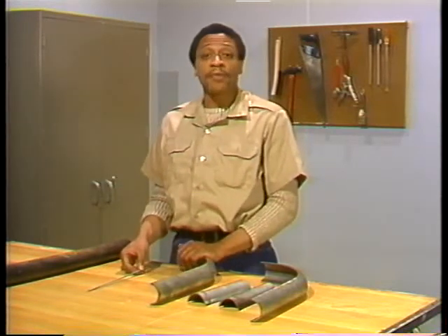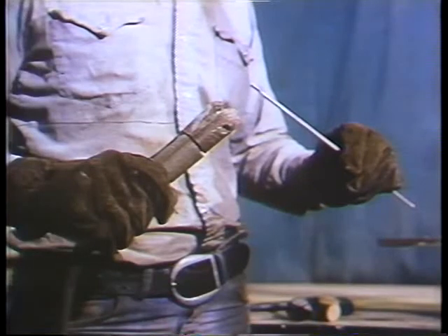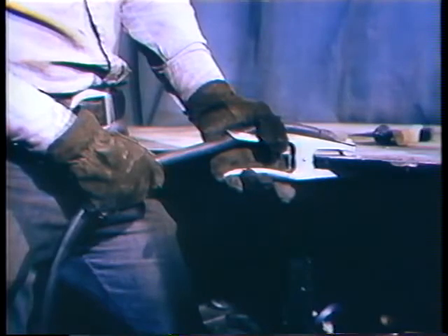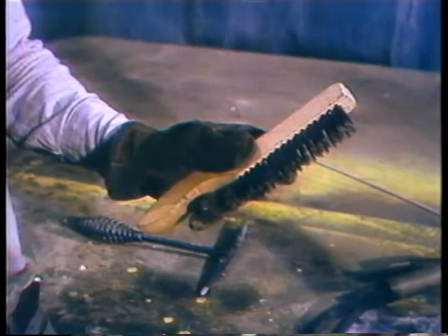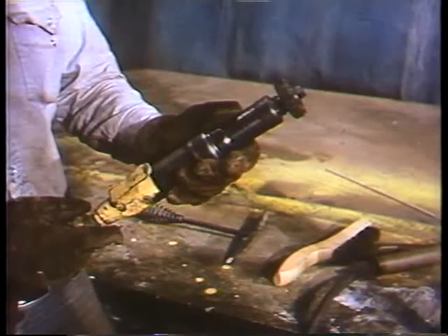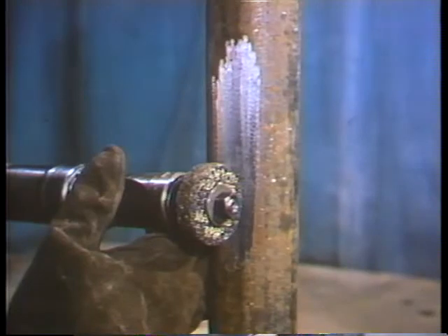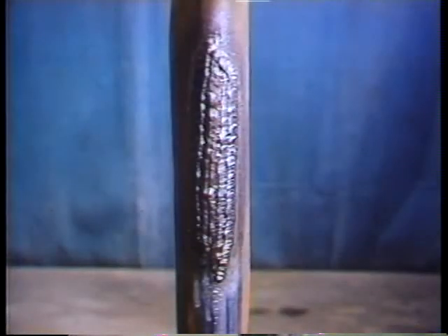Remember, the tools and equipment you'll need to do a clad repair are weld rod and a rod holder, a grounding cable, a slag hammer, a wire brush, and a grinder. The steps in the repair are clean the area to be clad and apply the weld metal. Again, cladding is used to thicken and reinforce the tube wall. It's used to repair tube thinning caused by corrosion and erosion.